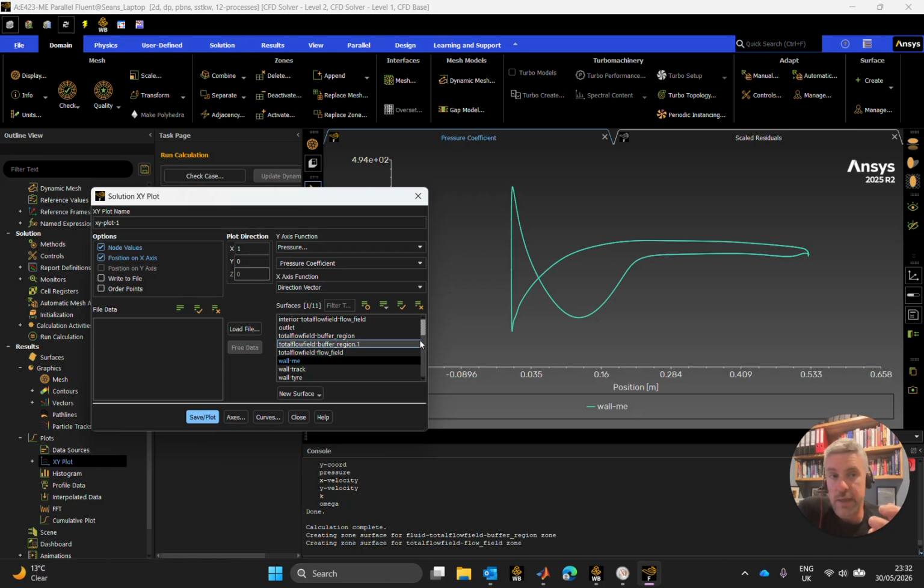So the angle of attack doesn't really have the same sort of effect that you might think it does on lift. It is really the energy at the trailing edge that's going to have the most effect on this. At the minute, we have no energy on the trailing edge. Pressure coefficient there is adverse, and that's apparent. So what we want to do is get more energy onto that.